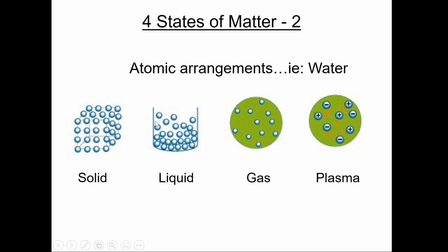They're in the air. So what they're trying to tell us by this is when something is in liquid form and held in a liquid form, something gets depleted, something gets burned off, something turns into fume. And we know that there are fumes that come off of these welding processes, right? It's no secret. But here's what we need to know: the longer we keep a piece of material in a liquid form, the more the metallurgy changes forever.